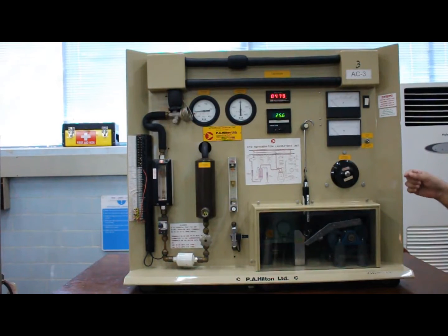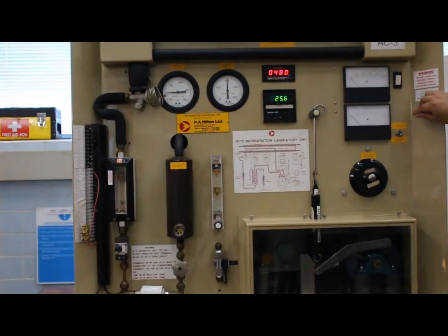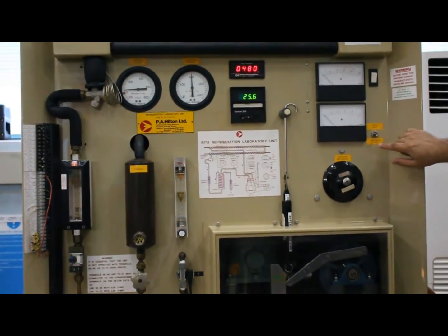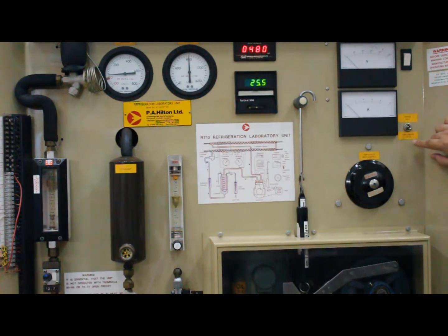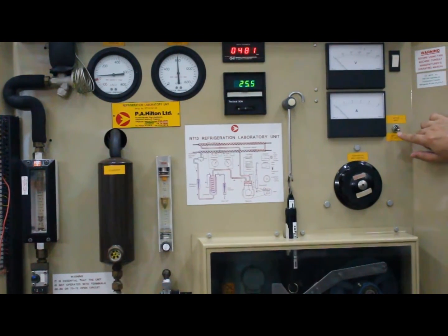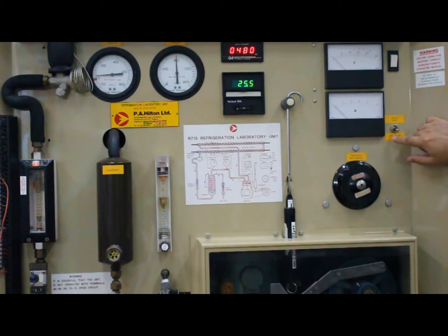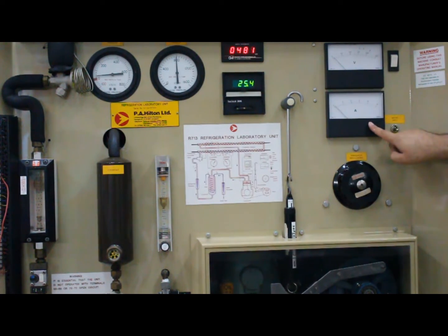Another variation that you can make in this entire experiment is with the help of the type of input that you give. For example, if you are going to vary the evaporator side input, that is the energy input you are giving to the evaporator side, you must use this switch. If this switch is pushed downwards, in the down mode, it shows the input in the form of the product of volts and amperes, and this is equivalent to the amount of heat that is being supplied by the heater into the evaporator.